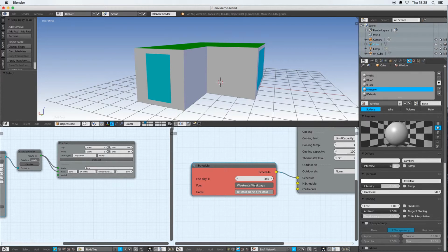For the weekdays, and I've actually done it the wrong way around, I'm sorry. I've specified a weekdays heating system when it should be weekends. So I'm going to specify weekends first. The way we separate between these two day types is with a semicolon. So now I'm going to say 24, so the whole day, it's simply 0. So at weekends, for 24 hours, it's 0, and for weekdays, up until 8, it's off.